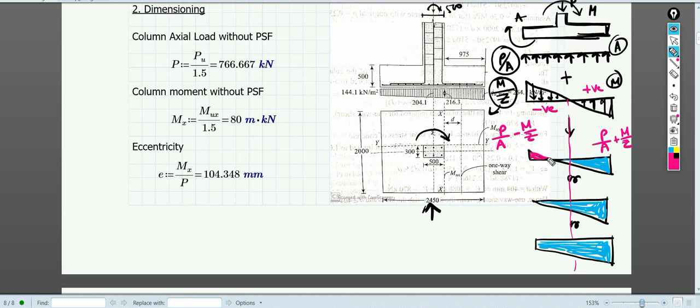Why? If there is tension over here, suppose I'm talking about this part where I'm having tension, in that case this part of the footing becomes useless for us, because this portion cannot transfer the load of the structure to the ground, because it will move upward. As the moment acts, ultimately the footing will tilt, and it will have a deflection or rotation, something like this, right? So as the tension develops, this portion becomes useless for us. We have only a limited portion available with us.